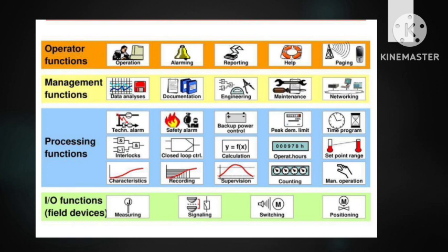2. Automation layer level. DDC controller. This layer consists of direct digital control, DDC, controllers, which receive input from the field devices, process the data, and execute control actions based on predefined algorithms. 3. Management level, centralized workstation. At this level, a centralized workstation serves as the brain of the BMS, providing a user interface for building operators to monitor system performance, adjust settings, and generate reports. Together, these components work seamlessly to ensure efficient control and management of building systems.